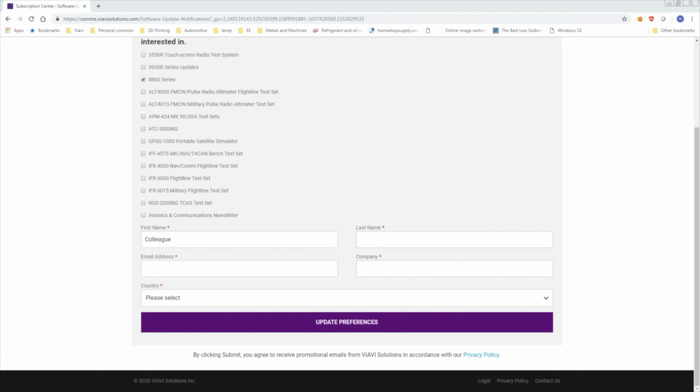Generally speaking, my view has always been that while we know that there is loss, if you had a VNA or a network analyzer, you could sweep it and you could probably characterize that attenuator and see how much phase shift there is in it and all that stuff. In reality, bear in mind, what we're doing here are pretty simple measurements. We're just simply checking transmit power and sensitivity for the most part.